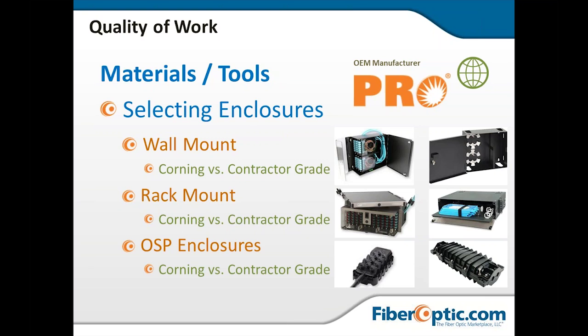Also, Corning units have very rounded edges. Not soft, it's metal, but more rounded edges. They kind of take some of the burrs and sharp corners out of the equation. When you're dealing with fiber, a lot of times when we deal with people who have something go down and we deal with emergency restoration, somebody just closed the door on a fiber jumper and snapped the pigtail or the cable that was coming in it, because it didn't have enough protection. It wasn't built and designed right.